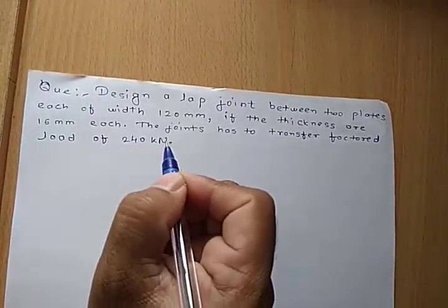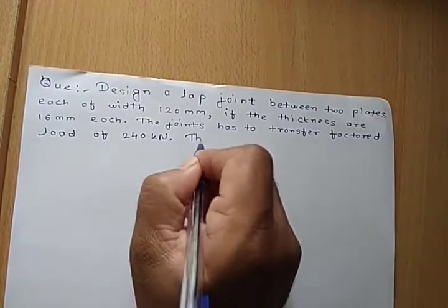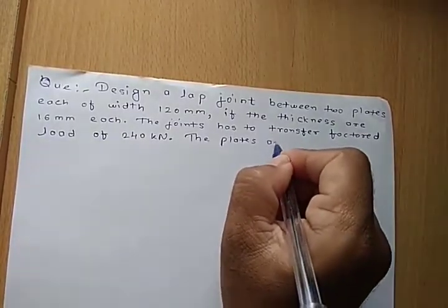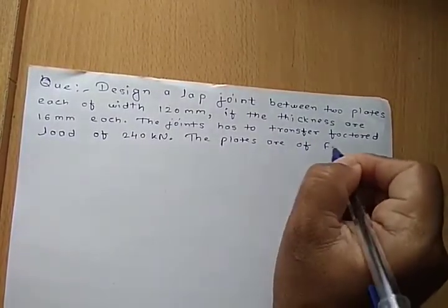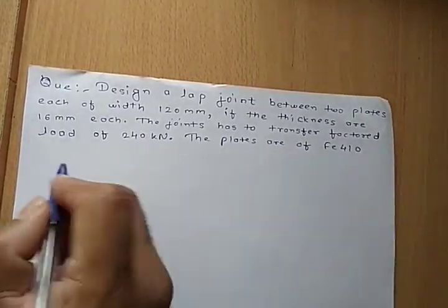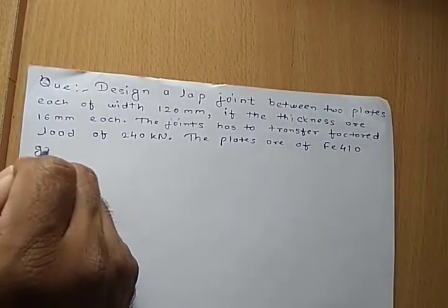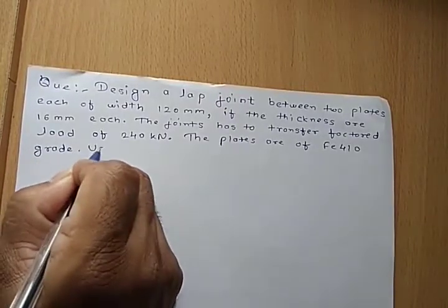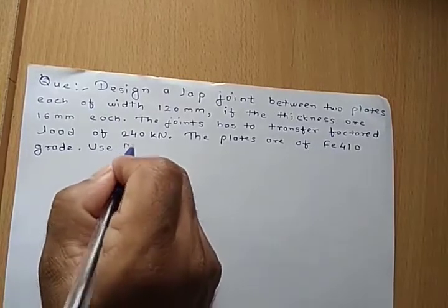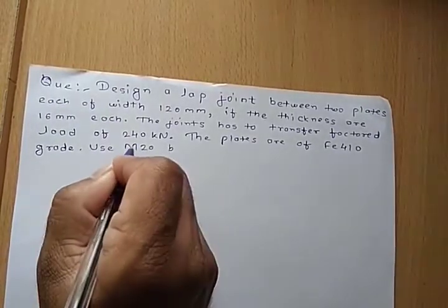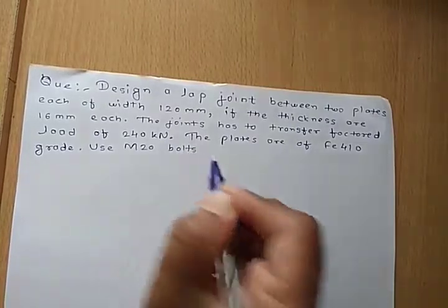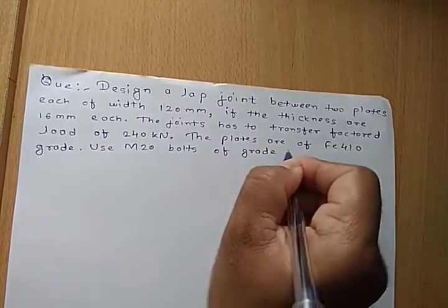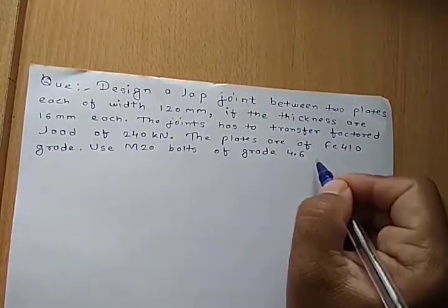The plates are of Fe410 grade. Use M20 grade of bolt, grade 4.6, of bearing type.